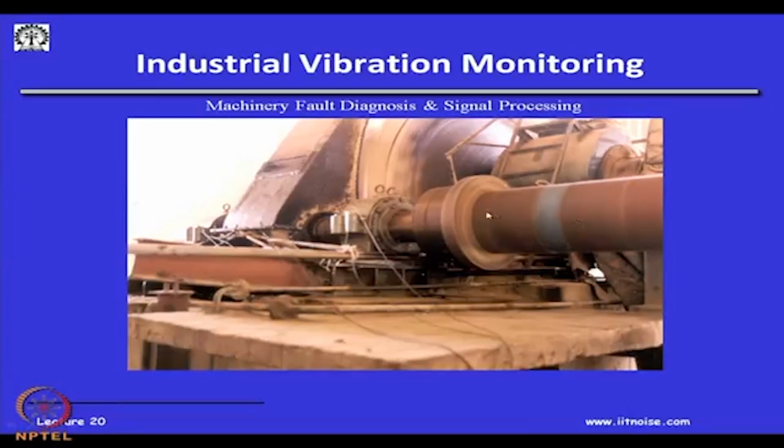Here you see a torsion shaft which is rotating, supported on bearing housings, and you will see a few cables coming out here. These are accelerometers which you cannot see here, installed just to record the vibration levels, and then we can bring these recordings back to the lab and do the analysis from a diagnostic point of view.